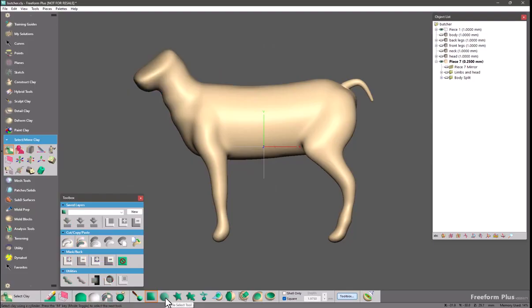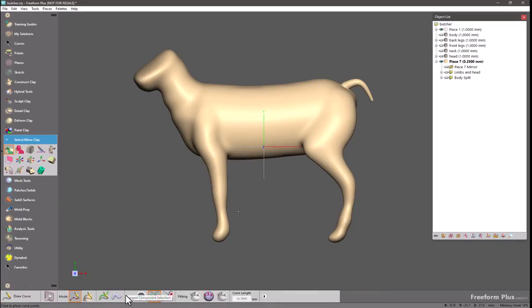We added a brand new circle select tool. This one here, the circle begins at the center of your click, and then you draw the radius out, and you can make circular selections. This is also handy because you can use the erase tool and then remove and have circular selections. So at times when this would have been more effort to create a sketch in order to create that type of selection or profile, now you can do this interactively within the selection tool.